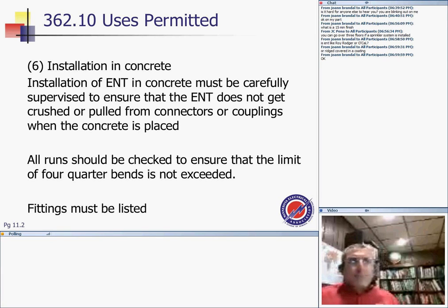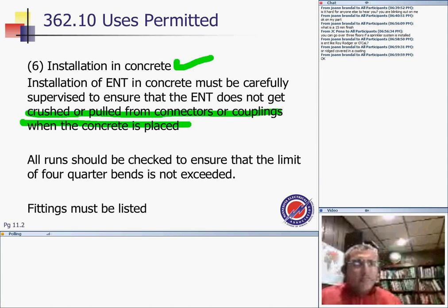Where's the advantage of it? Where can I use this baby? In concrete. You can bury it in concrete. ENT, you can put it in concrete, but make sure you don't get it crushed or pulled from the connectors. So a good application, guys, is directly buried in concrete. When you pull conductors, pay attention to crushing and keep it away from the fittings or the boxes and so forth.